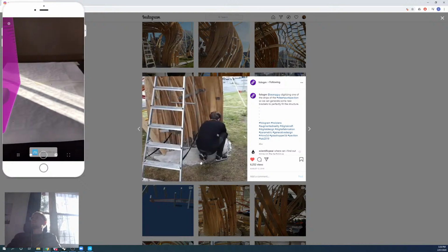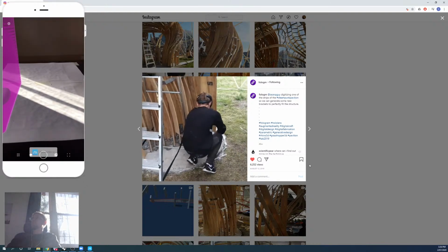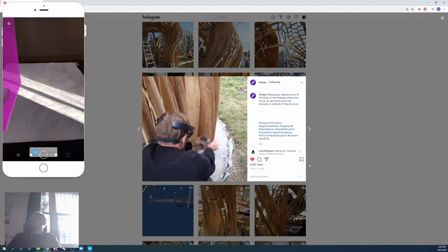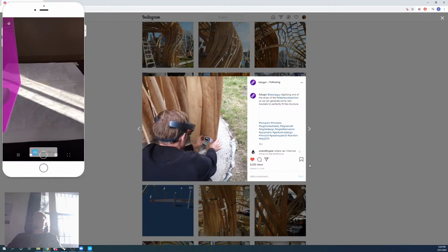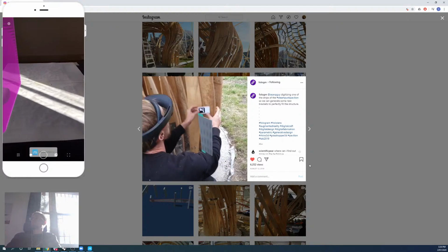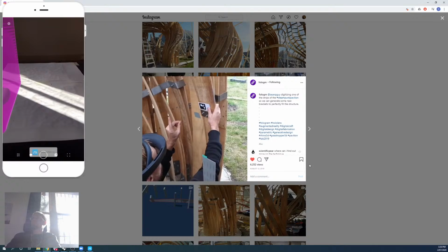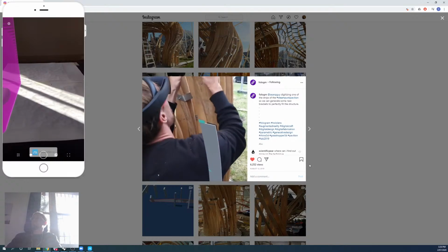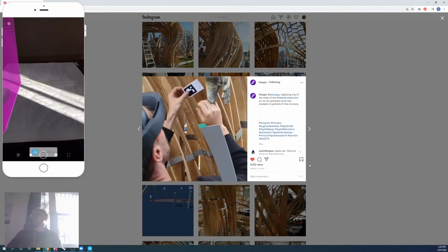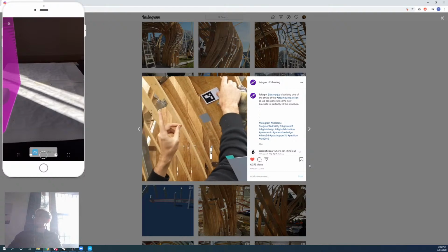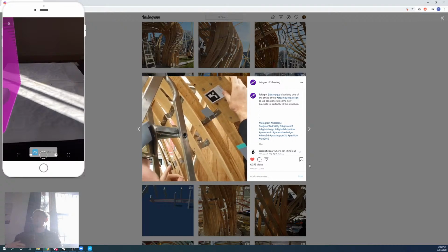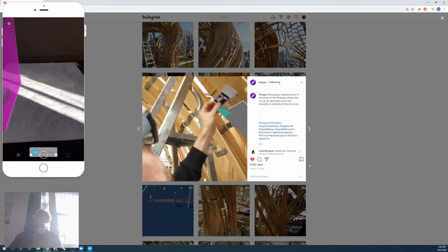Basically, when we were bending the steam bent timber and then assembling it on site with all of our steel pieces, we had a bit of an issue where some pieces weren't accurate to our 3D model. Some of our pieces of steel weren't actually fitting. So we were using Aruco markers to draw a lofted surface of each of the timber pieces. We'd create a low resolution scan of these timber strips all the way up, and you do like 5 or 6 of them, and then our engineer would say, well, you need a steel bracket in this position.